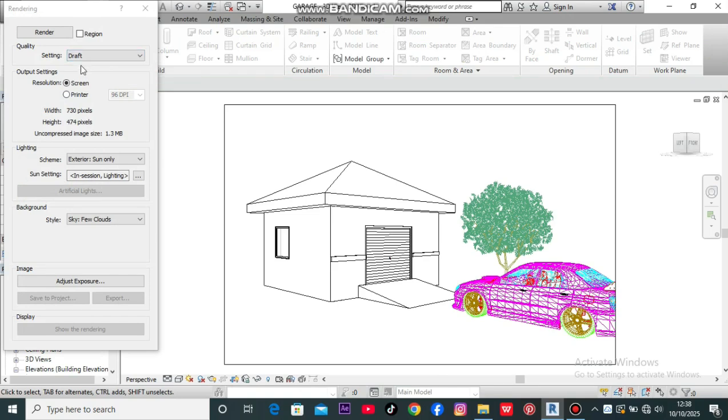So to start our render, just hit this little kettle icon here and render settings, which is very, very important. I don't know if you're gonna screenshot this or write it on paper, but make sure you keep a record of this. From draft to medium, because if we choose best, high, or something like that, it's gonna take very long for that matter. And when you choose draft, the image is going to look super drafty.